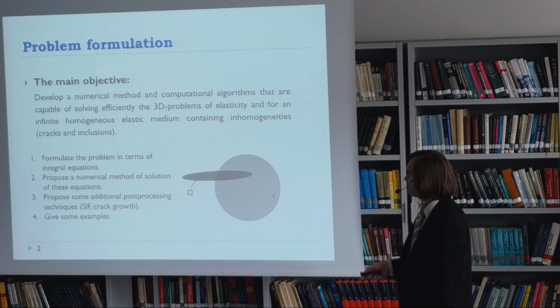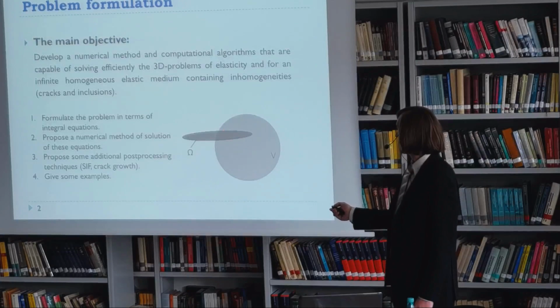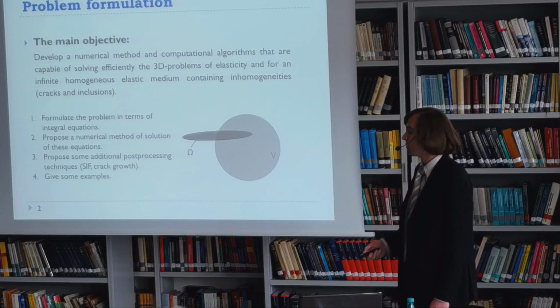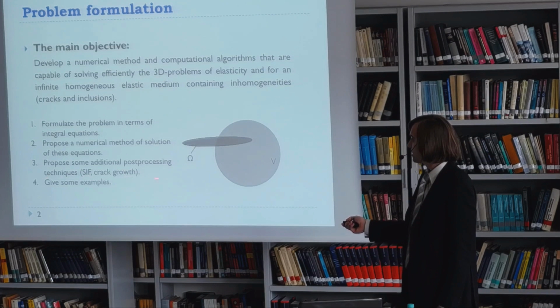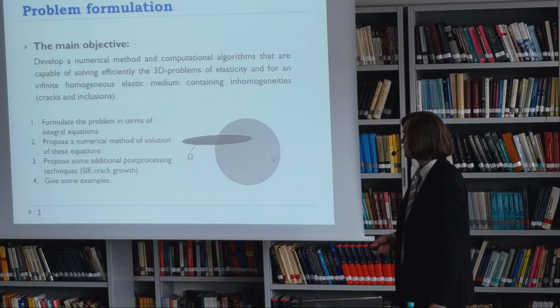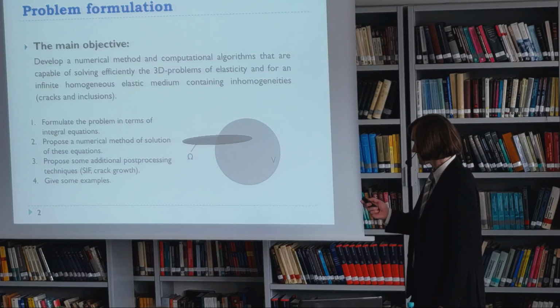So, what's the plan of this presentation? First of all, we're going to start with formulating this problem in terms of integral equations, which are boundary for cracks and 3D for inclusions. Then, of course, we're going to propose a numerical method of solution of these equations and some additional post-processing techniques. Mainly, we'll discuss calculation of stress intensity factors for the cracks, and we'll study the problem of crack propagation, crack growth in such media. And of course, we're going to give you some examples of calculations we have done.